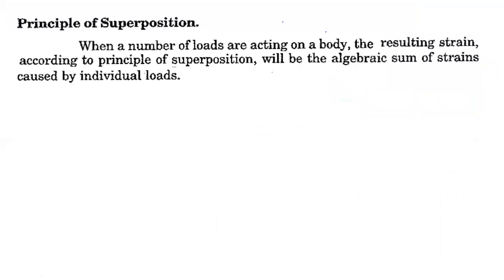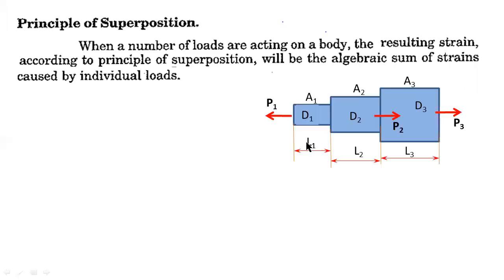Now I am going to explain one basic point, that is the principle of superposition. When a number of loads are acting on a body, the resulting strain according to the principle of superposition will be the algebraic sum of the strains caused by individual loads. This is the example for a principle of superposition.